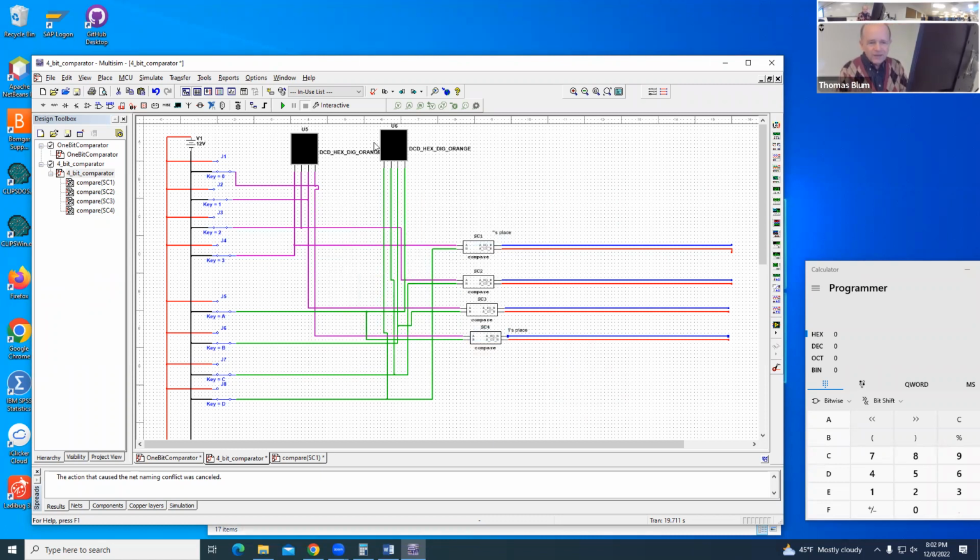And I have to say what kind of 4-bit number I have. I am going to have an unsigned number, so these numbers are purely positive. I'm not worried about signed bits. I'm not doing 2's complement. If I were doing two's complement, I'd have to treat the most significant bit, or the sign bit, differently. But I'm going to assume this is an unsigned 4-bit number comparator.